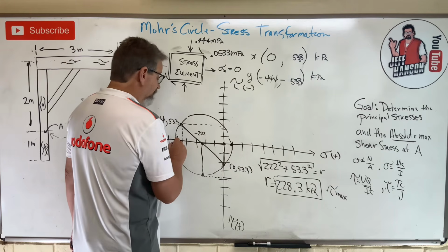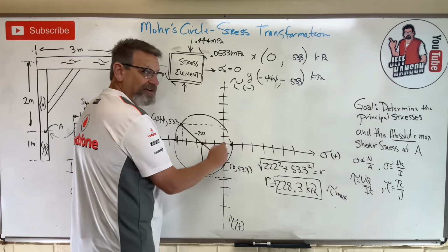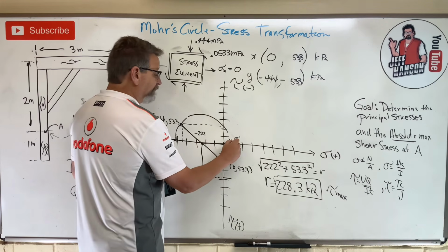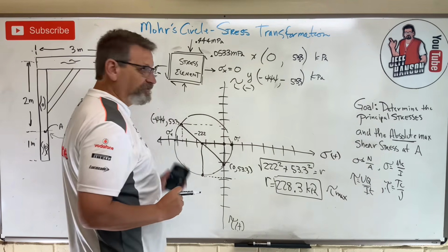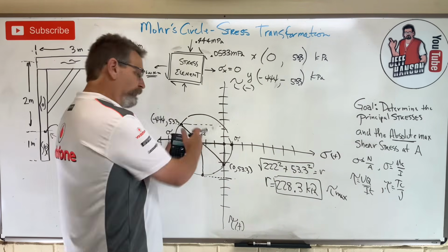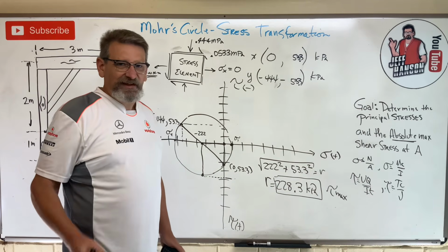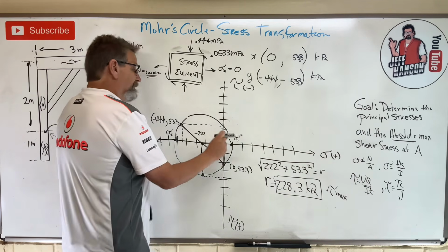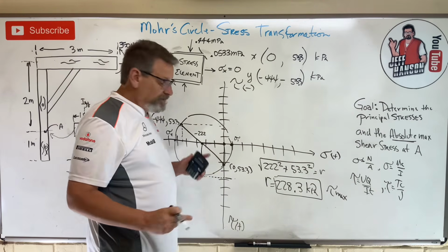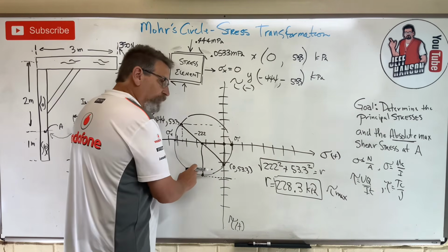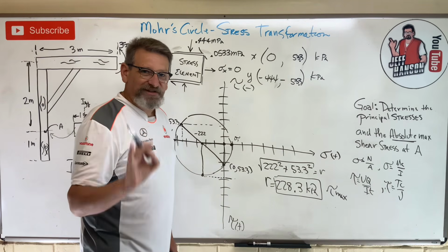If the Mohr circle straddles this axis, if these 2 points, sigma 1 and sigma 2, if one of them's positive, one of them's negative, then that circle is going to have the absolute max every single time. If sigma 1 is positive and sigma 2 is negative, then that Mohr circle is going to contain the absolute max shear stress every single time.